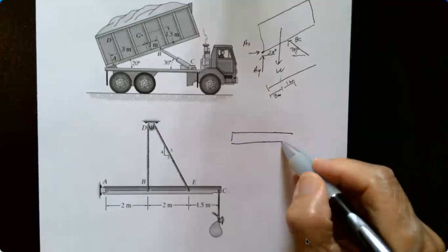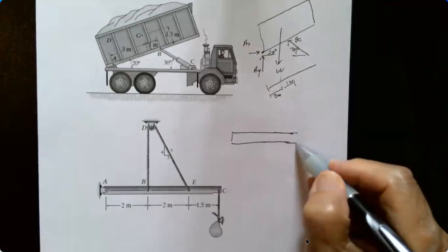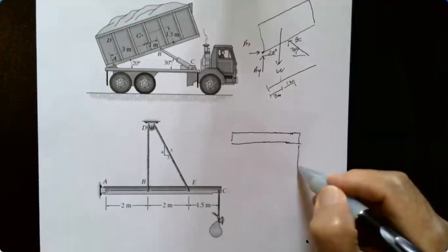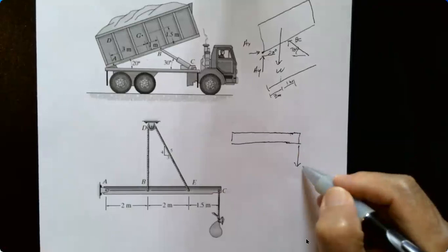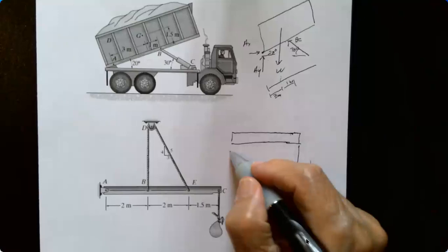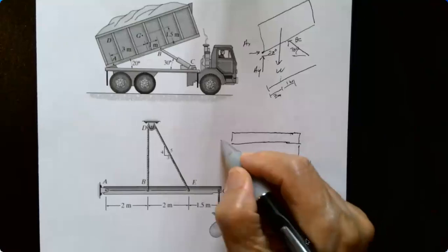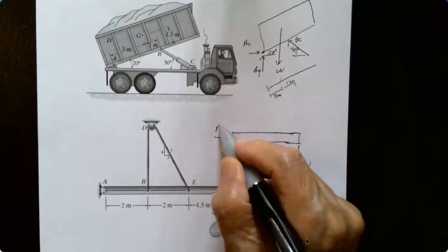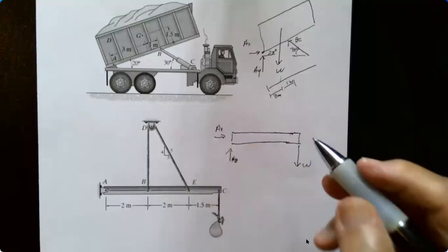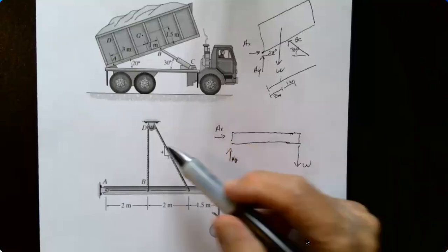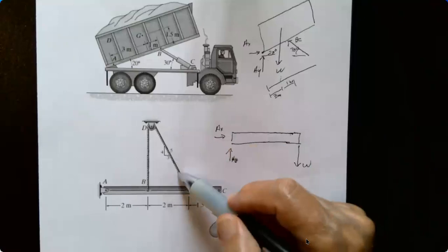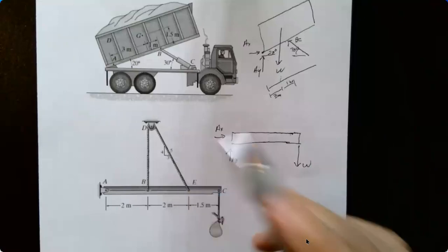Okay. So what I have to draw this up here. And we also probably have the weight of the beam itself in here that we're looking at. So I have a load, or W, that we have at A. We have an A sub Y, an A sub X. Okay, the cable. There's tension in this cable, and it's the same. It's attached here at E and B. And remember what free body diagram does.